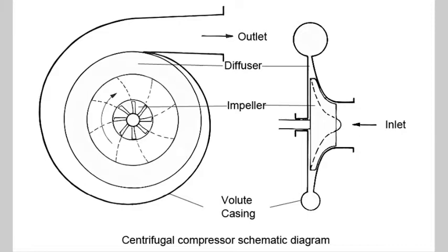Centrifugal compressor. Centrifugal compressor is usually used in large capacity refrigerating systems. In this compressor, the vapor is moved in a circular motion known as centrifugal force. An impeller, which is a disc with radial blades, spins rapidly inside this housing, causing the gas to gain velocity. A diffuser converts this energy into pressure energy and it is then discharged into the condenser. The pumping efficiency increases with speed, hence this type of compressor is designed to operate at high speed.